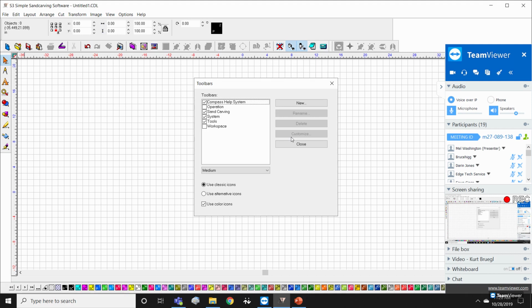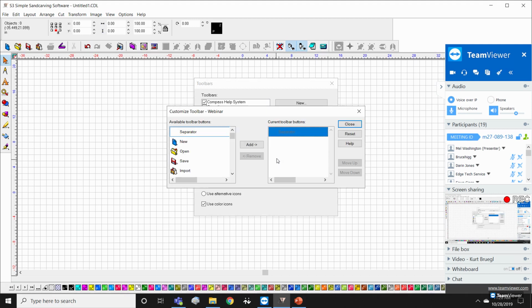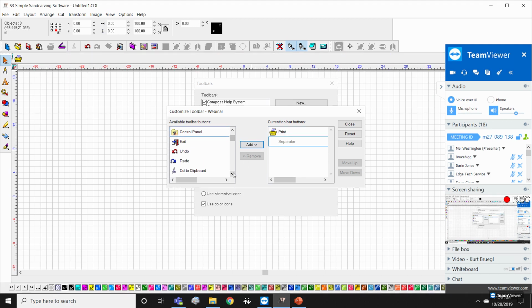I can go customize, and I can create a new toolbar, and I could call it anything I want. Let's just call this one webinar. All right, so I have webinar up. And now what I can do is go through all of the different commands there are in the software and add the ones that I know I'm going to use frequently. So I can make my own customizable toolbar.